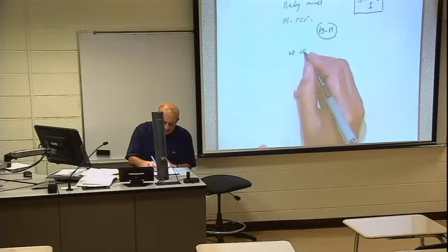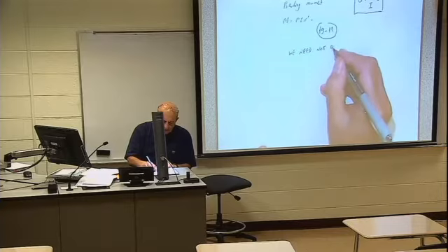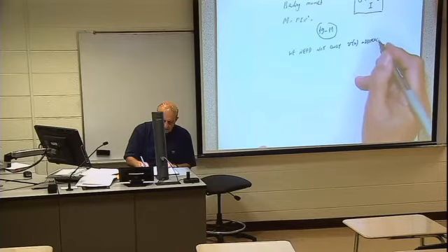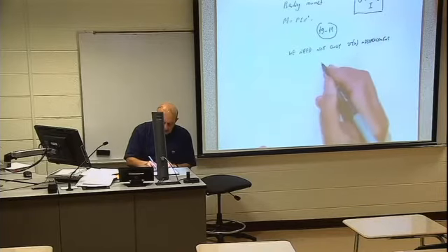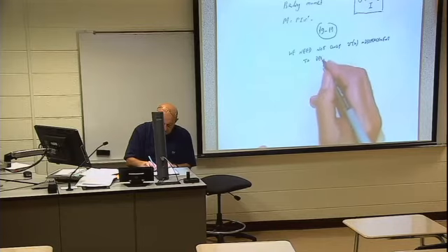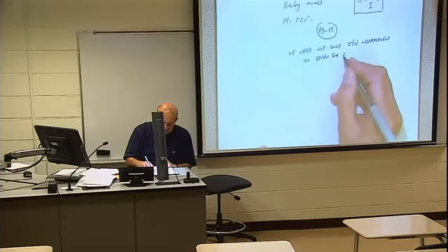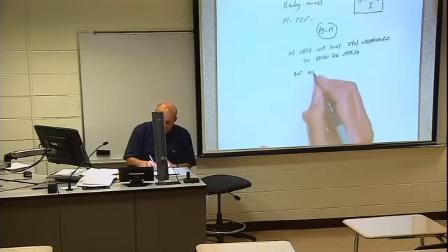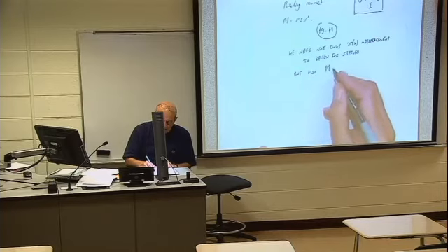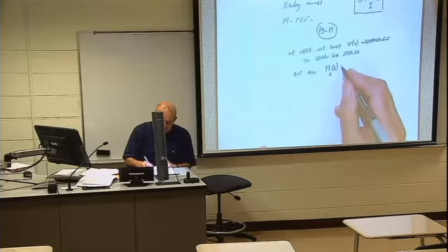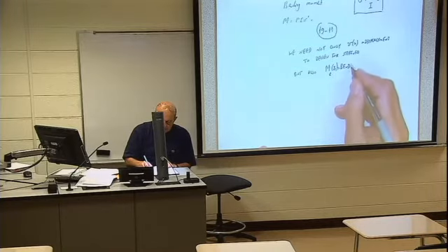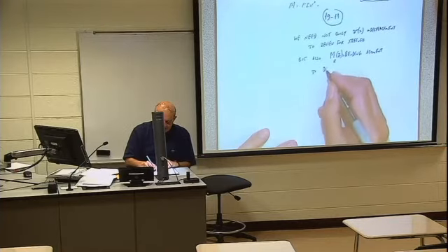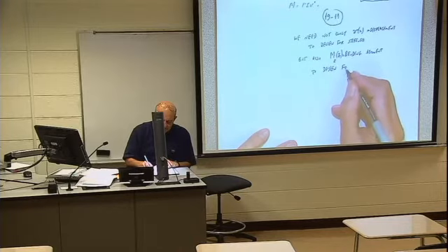We need not only V of x, displacement, and to design for stiffness, but also bending moment, Mz of x, to design for strength.